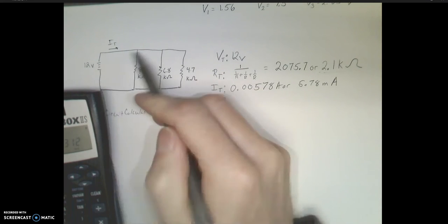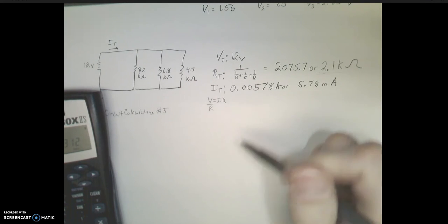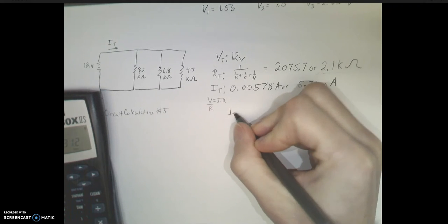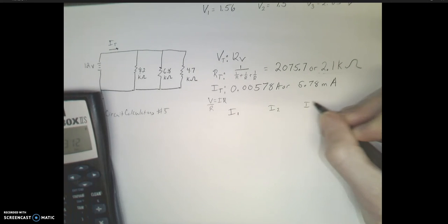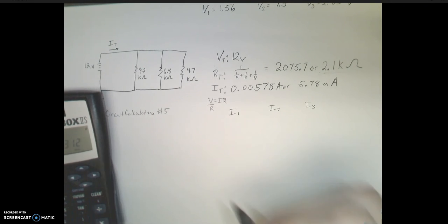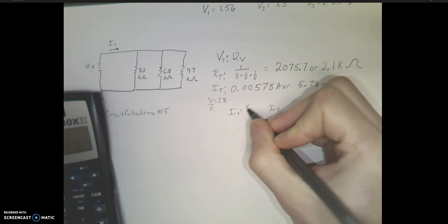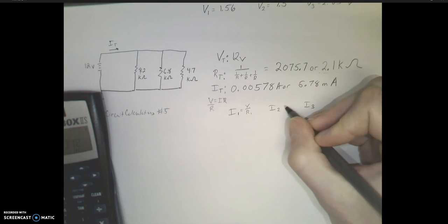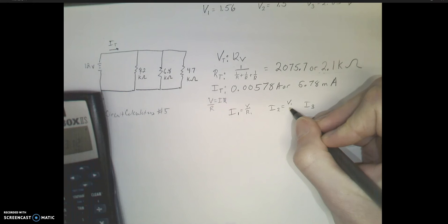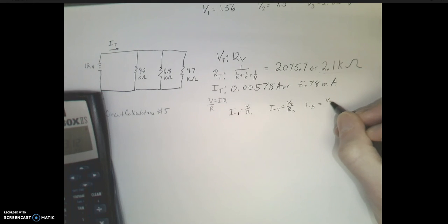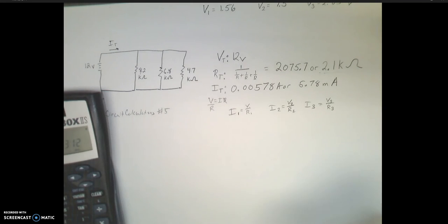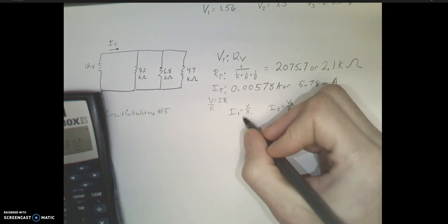So now we're looking back. We've got a parallel circuit. Inside that parallel circuit, voltage stays the same. So the voltage at each one of those resistors is 12 volts. So now we've got to find the current at each one of those 3 resistors. So same formula, V equals IR. So total current at each individual spot is equal to the voltage there divided by the resistance at that individual component. So what we're going to do for each individual resistor, take 12 divided by that resistor value.